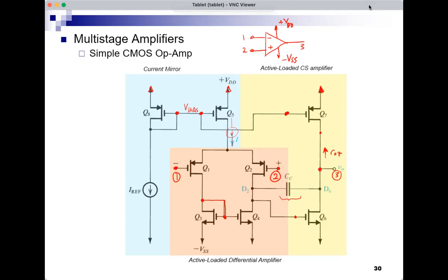So what is this capacitor doing and why did we add it? This will bring us back to the discussion about the open loop gain of an op-amp and how we sacrifice it to stabilize the operational amplifier. We said that we introduce a pole at a very low frequency. And when we do that, the gain would drop starting at this very small frequency. And that makes the op-amp stable. Okay, so we had to introduce a pole in the circuit.